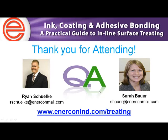This is a really easy way to measure if you do have a contact angle meter. I will note, though, only if you're working with a completely flat surface is this a good measurement. If you are working with a three-dimensional object, dyne solution is really your go-to for surface energy measurement because you can't get an accurate reading from a contact angle.